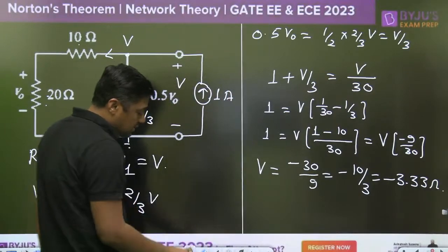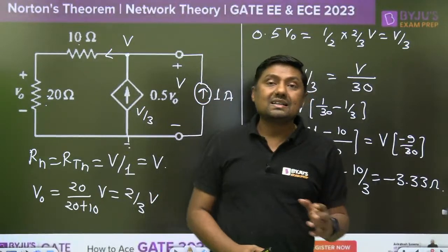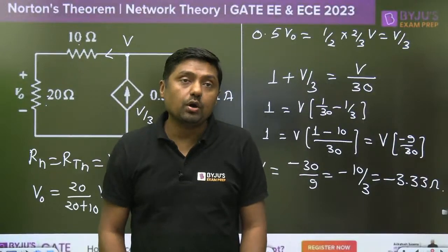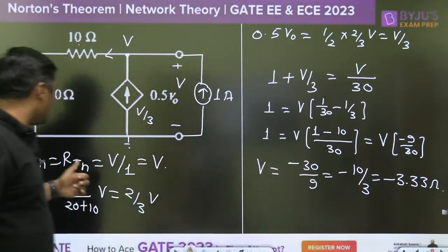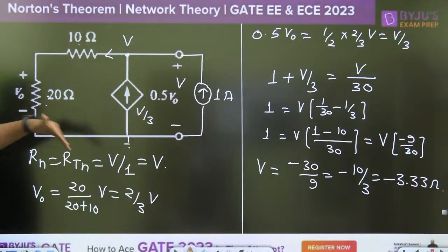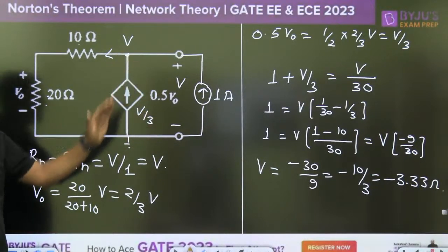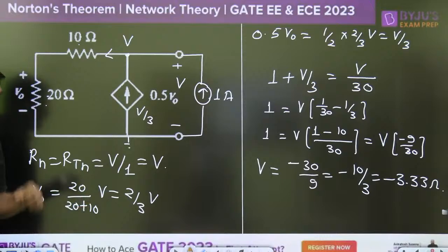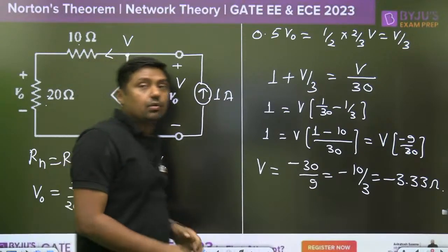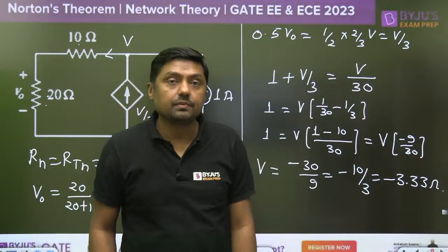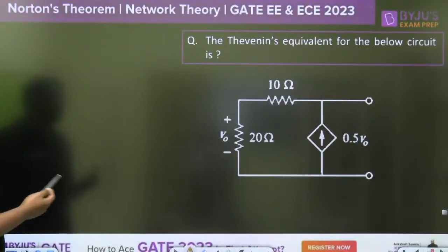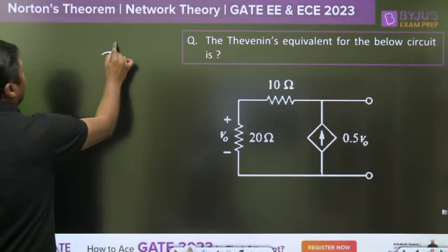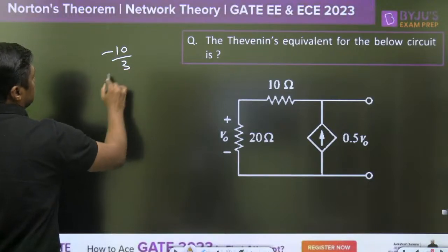And these are the methods of how to solve the Thevenin's equivalent. Okay, so this is a negative resistance. V is nothing but RTH, and that is the method: 1 ampere current source, and simply V by I, that is the V. You have to find the value. Negative value. Okay, absolutely right. Again negative, same logic. If we are getting a negative value, it means an amplifier.